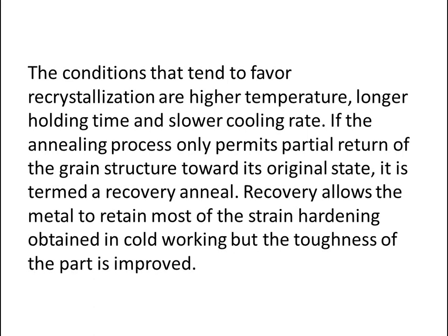If the annealing process only permits partial return of the grain structure towards its original state, it is termed a recovery anneal. Recovery allows the metal to retain most of the strain hardening obtained in cold working, but the toughness of the part is improved.